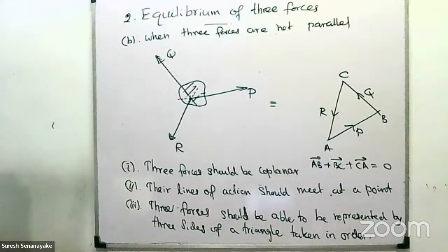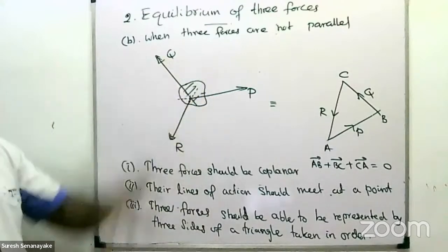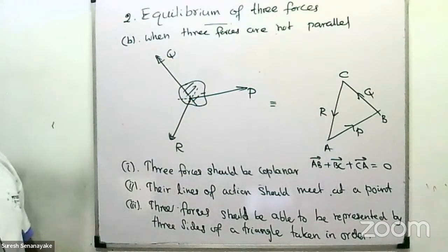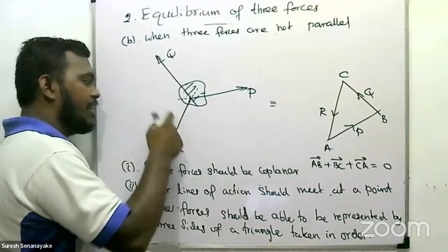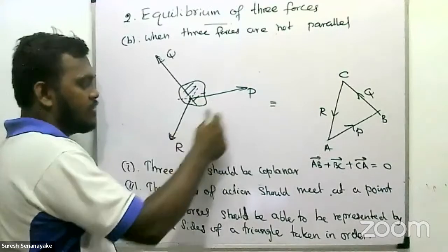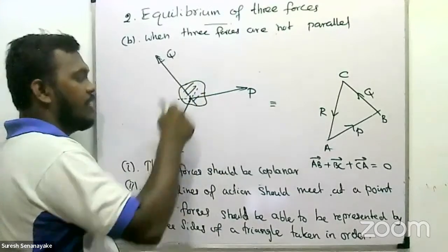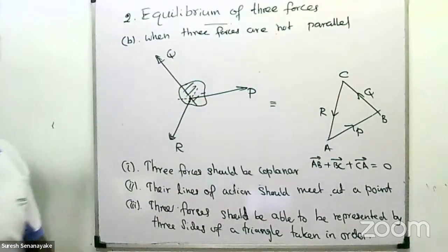And not only that, in this kind of case, we can apply Lami's theorem. But Lami's theorem is not in the syllabus. But we can say that this force divided by the sine of the angle between the other two forces, and this force divided by the sine of the angle between these two forces, and this force divided by the sine of this angle, must be equal to each other.